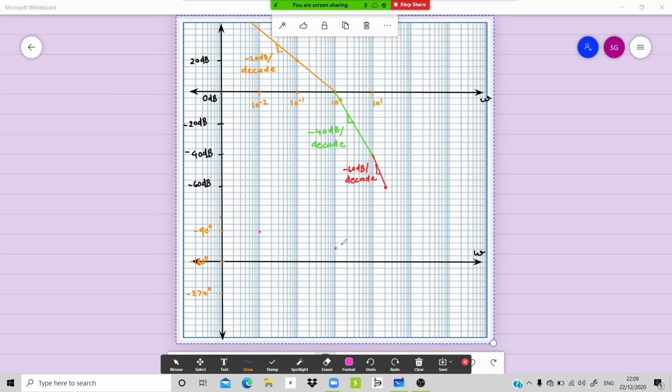Okay. Then another critical point that we are having is 10 raised to 1. For 10 raised to 1, the angle is 219. So 219 means we can say 220, right? So 180 plus 18, 198 plus 18, 216. Okay, so somewhere on the second division.